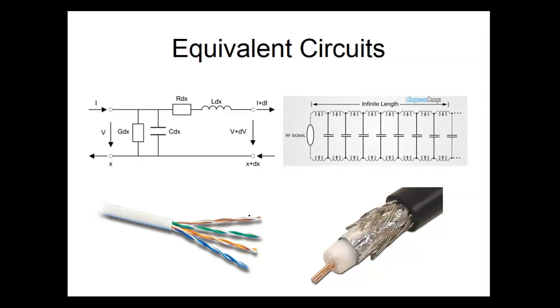So we don't want a high impedance output amplifier connected to a low impedance input. A lot of people can't understand why we go through stages in an amplifier. We start off with a real high impedance because you have high impedance coming in on your input, and we move toward low impedance as we move toward your speakers. Your speakers have really, really low impedance.